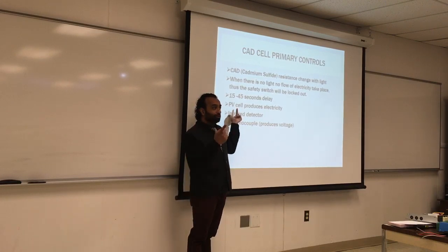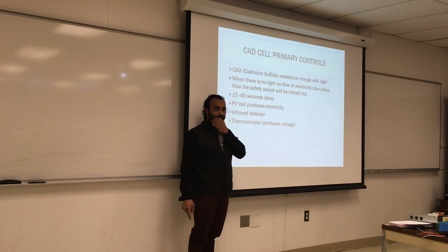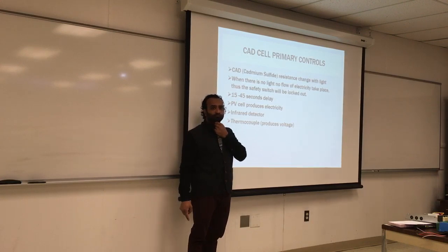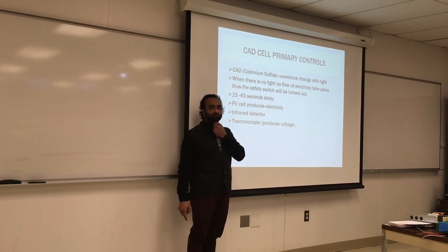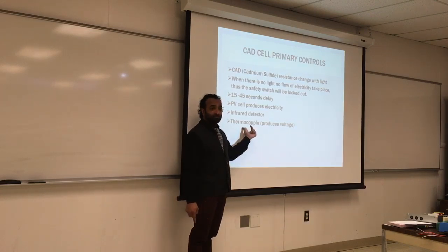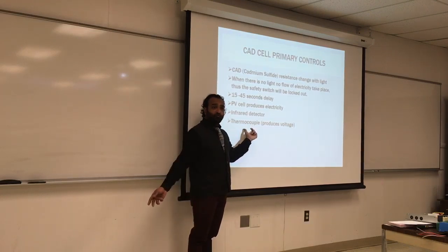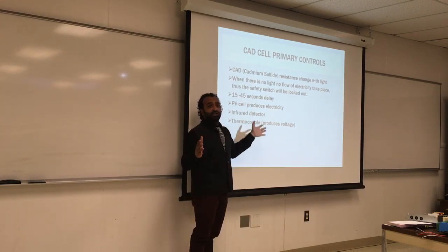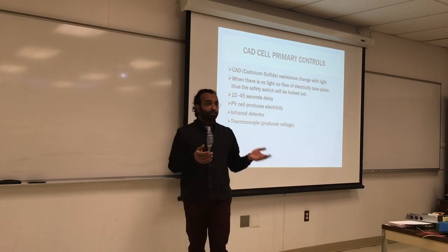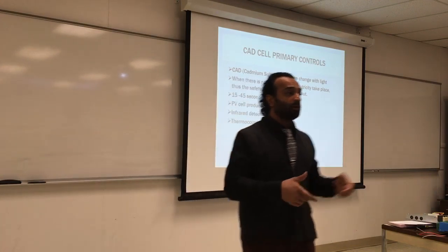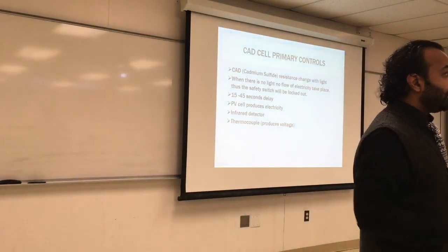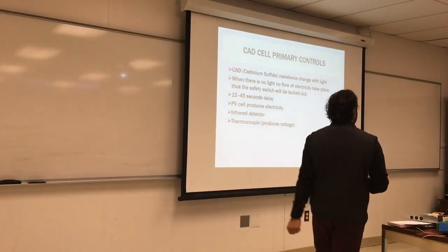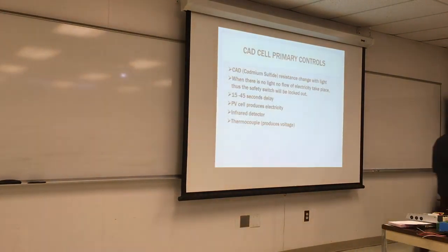It's about visual. So you're saying these detect heat because of other properties that are from the flame? Yeah. This one detects heat. Flame rod detects ions. The other ones are optical. They just see the light. They look at the light. That's why they call it optical, and that's why sometimes they put a magnifying glass on it so you can absorb how much light comes from the fire.